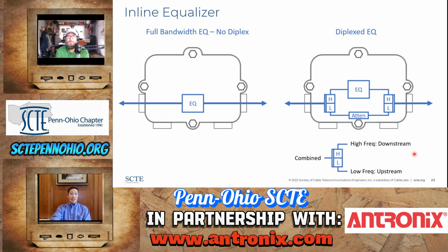Very good. That's exactly right, there are two different types, and more of the legacy equalizers in the field are the one on the right, the diplex versions. You can see that. And the diplex version, what is diplexer here? It's combining frequencies, like we mentioned. H is the higher frequency, which is downstream. L is the lower frequency band, which is the upstream.